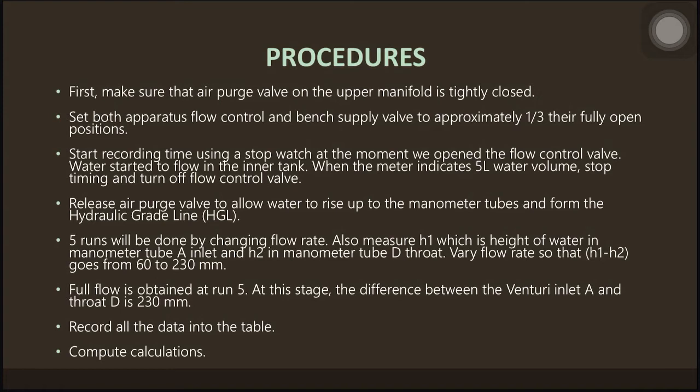Alright. Assalamualaikum warahmatullahi ta'ala wabarakatuh. My name is Muhammad Azrul Hisham bin Azmi. I would like to present about the procedures of this experiment. First thing first, make sure that the air purge valve on the upper manifold is tightly closed. Second, set both the apparatus flow control and bench supply valve to approximately 1/3 of their fully open position.